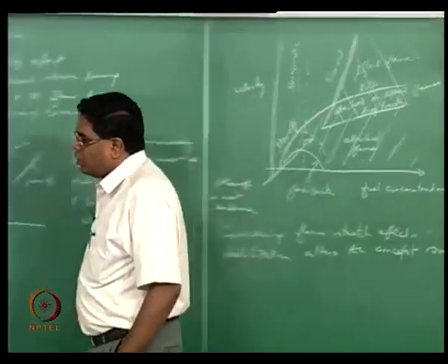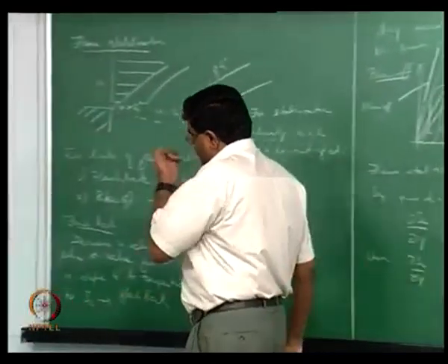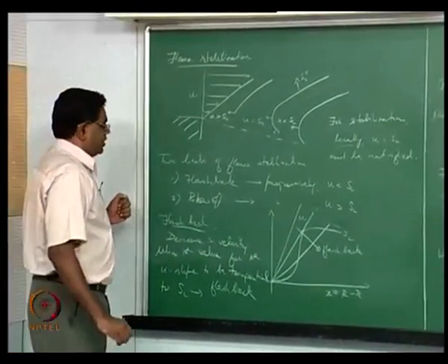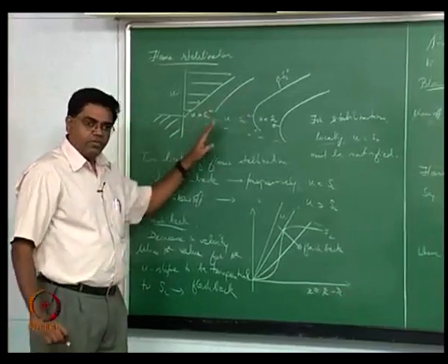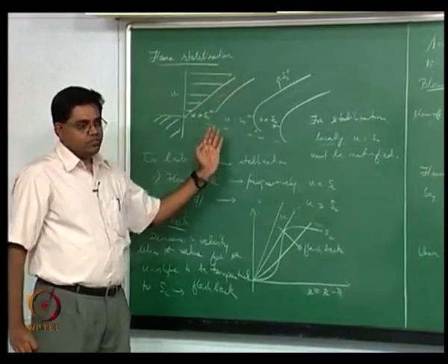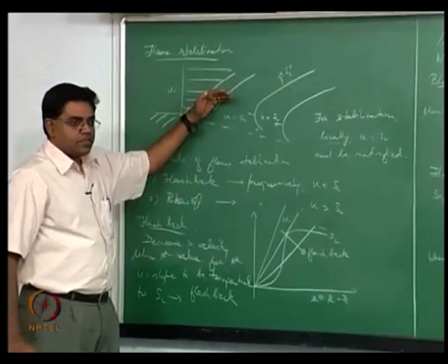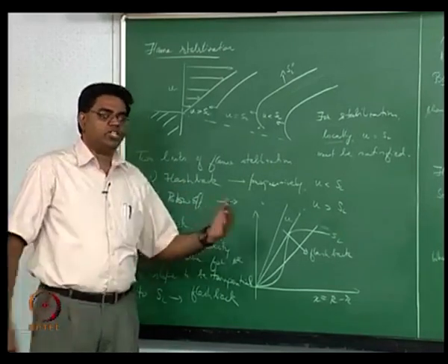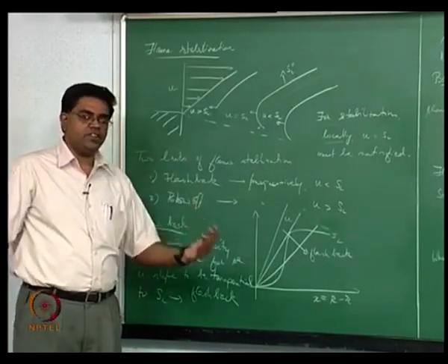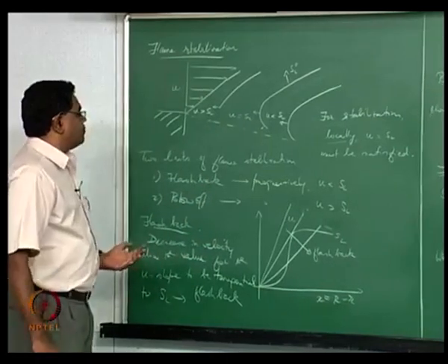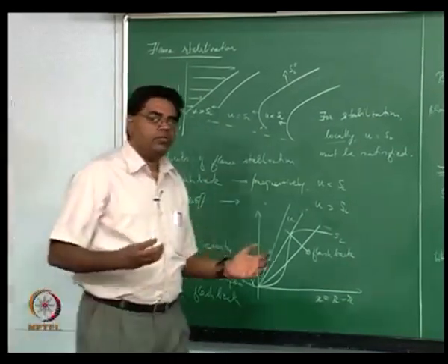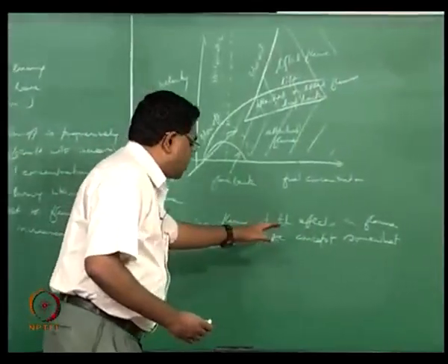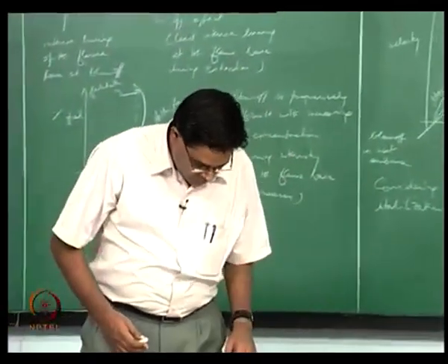We could do this. We know how the SL changes with flame curvature and flow divergence, as we have seen yesterday, and we could take into account a diluting environment and a progressively changing fuel concentration or reactant concentration effect on SL. So you can take into account a spatially varying SL because of spatially varying concentrations of reactants, and all these things can be taken into account in a computation, right? In a way we want to calculate this and take this into account, and that changes things somewhat.